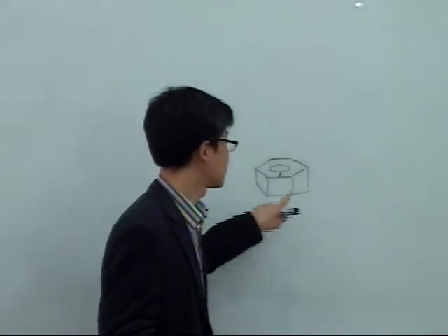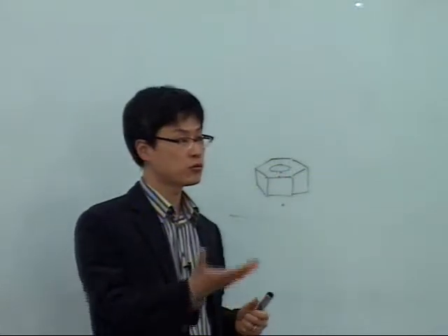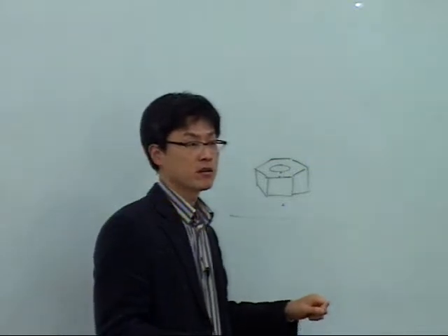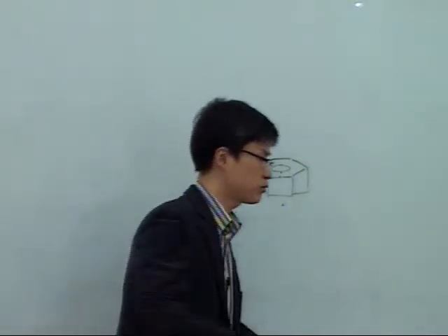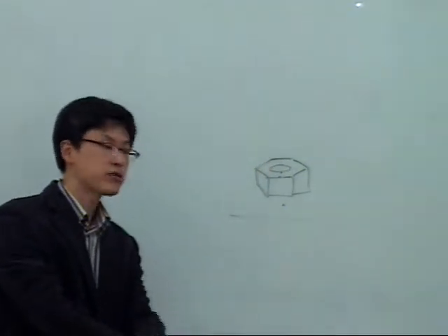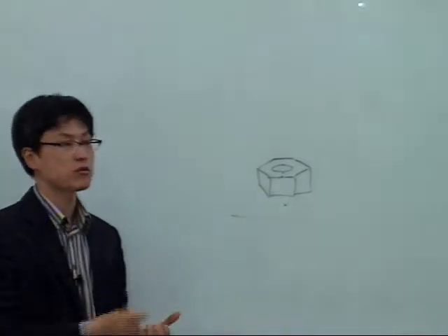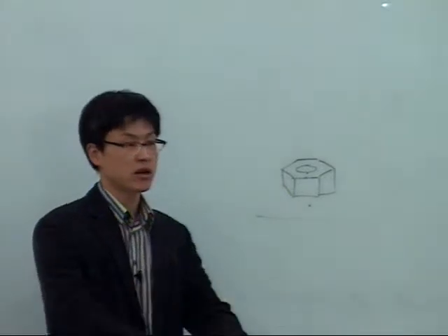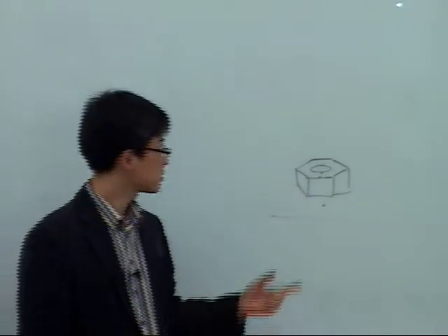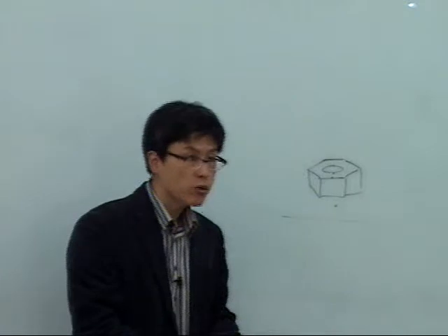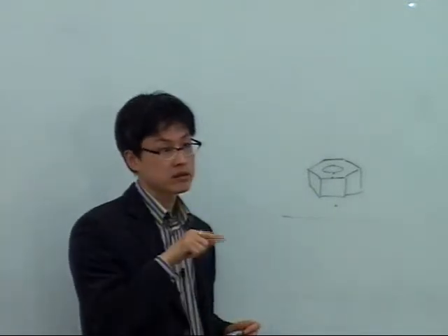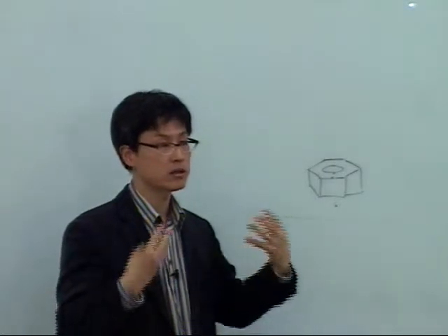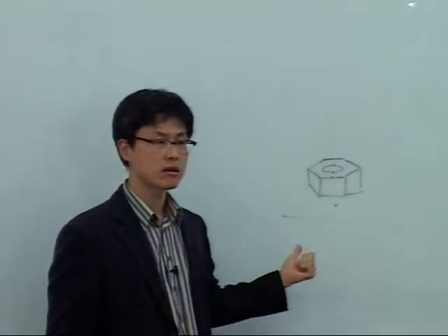Without this sign, do you know the torque wrench? Yeah. Without this sign, you have to put your torque wrench on and measure whether this bolt is secured with the right amount of torque or not. But checking every bolt is a waste of time. So when the right torque is applied, you mark it. And if it's misaligned, then it automatically tells its own status. It's an andon.